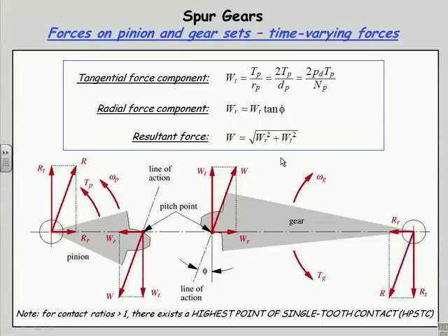It's a line normal to the tangency between the two things that are pushing on one another, in this case the teeth. And as I explained to you in respect to the involute gear tooth shape, the magic of the involute is that that line always stays at that 20 degrees, and for all positions of any teeth in the mesh, the point of contact will lie on that line, and that's what gives us the constant ratio.